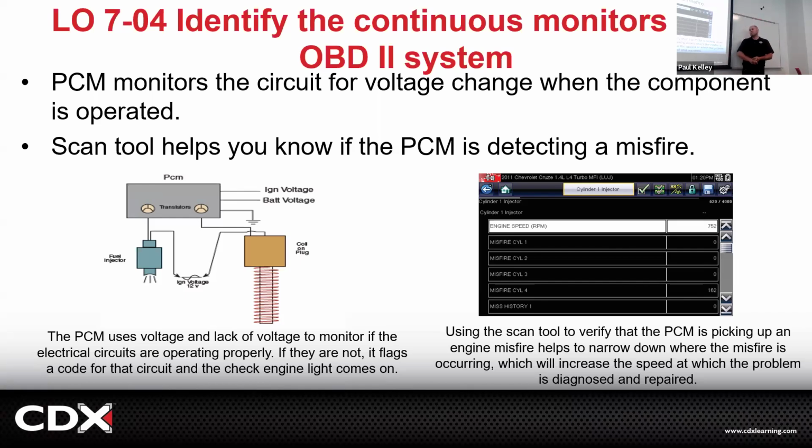But I'm just being really honest though. It's the truth. When it's a misfire code or one of these more performance type codes, it doesn't necessarily list the part, and really people don't know what to do. So the way that we'd go about that is more strategy based. What could cause a misfire? It could be no compression.